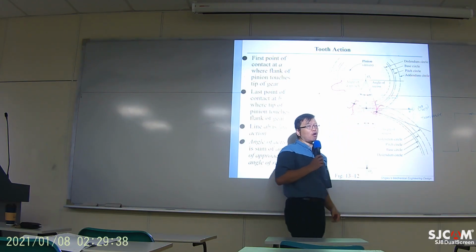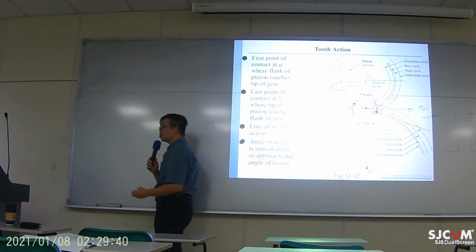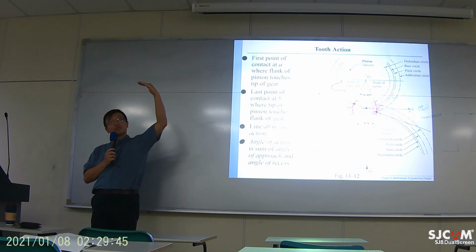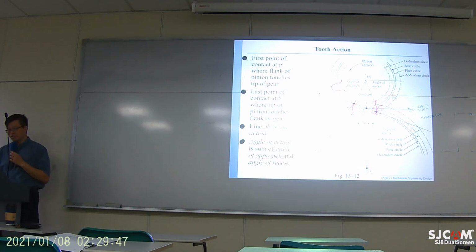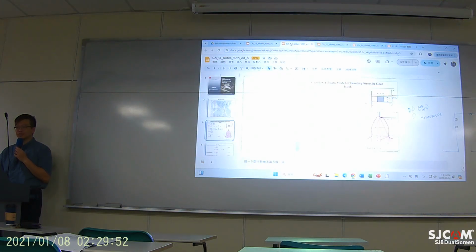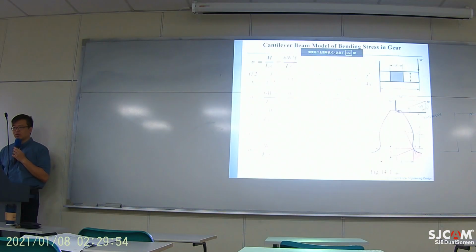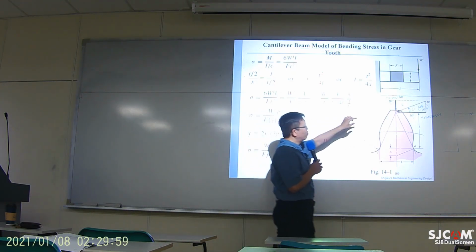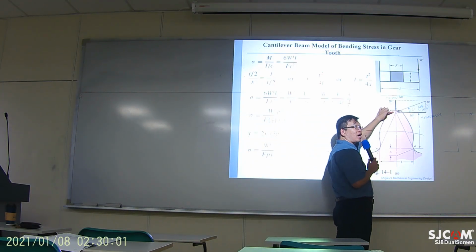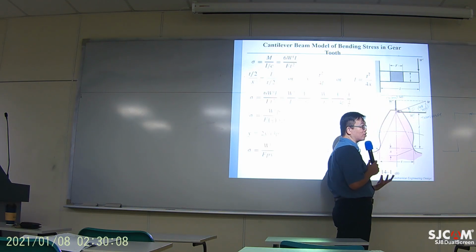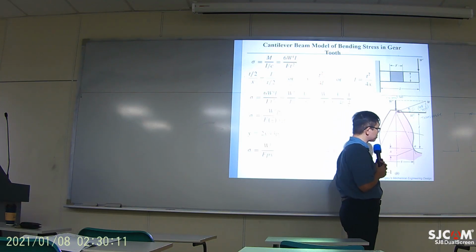So why do we only study the load condition when the force is pushing the tip? Because that's the worst case condition. Right at this particular moment, when we have force pushing at the very top, that's the worst loading condition. And for mechanical design, we study for the worst stress condition.